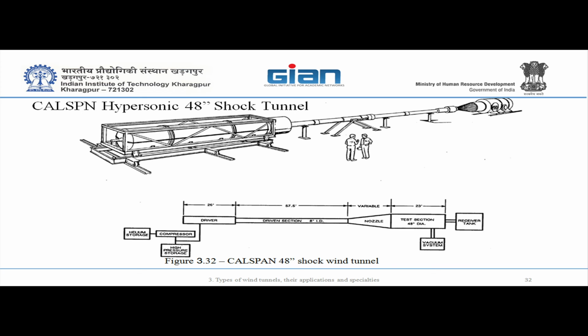So what you do is run a shock tunnel. We'll discuss the principle of shock tunnels and shock tubes later. Generally speaking, the principle of shock tube and shock tunnel is that you run a shock along your tube, and the flow behind the shock is actually the flow over the model. The shock is running in the tube over your model, and you have a bulk of certain charged air, and this is the test. So the test may take 2 milliseconds, 3 milliseconds, 4 milliseconds.